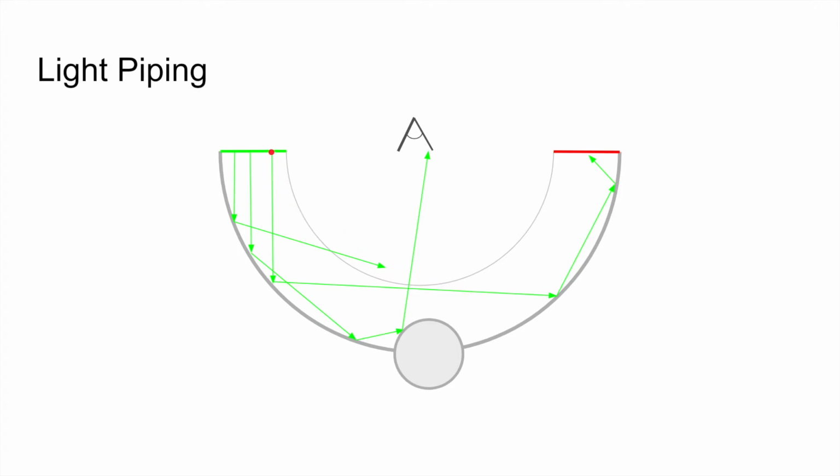In the actual sensor design, half of this is the rigid part and half is the rubber part. So some of the light that stays contained within the rigid part may escape at some point and come into the silicone and fill in these areas behind a point of deformation. Even though it hasn't been thoroughly tested, it seems like multiple contacts won't be an issue for this sensor.